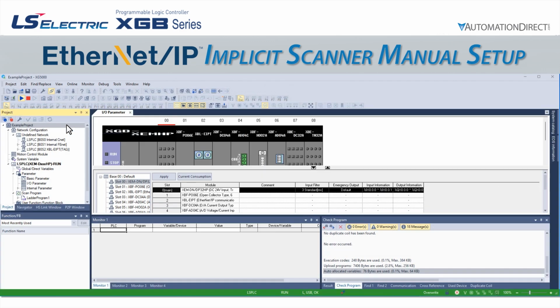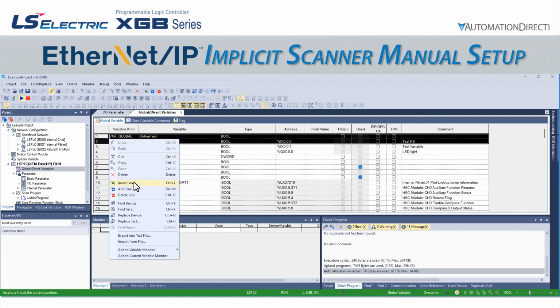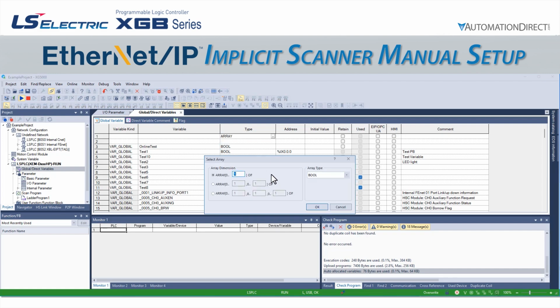Let's start by creating an input array and output array in the PLC memory. We will use these two arrays as the first stop for all data from this Ethernet IP connection once it is established. Let's go to the project window on the left side of the screen and double-click on Global/Direct Variables. This will open the Global/Direct Variables tab, and we will insert 2 rows. If we select a type of array and then click off of the selection, the software will open the Select Array pop-up window, and we will set up a 1D array of 0 to 15 elements. This corresponds to 32 bytes of information.